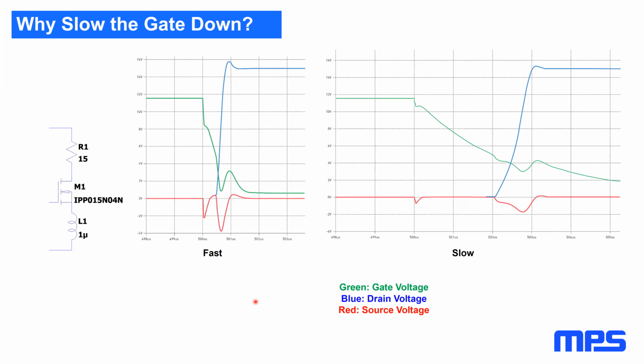From there, that'll give you a minimum. So there's no disadvantage to using a bigger gate driver because you can always slow it down. You can always insert some resistance. The downside is higher current gate drivers are going to cost more money, and quite often they're physically larger. But there's no downside because you can always slow things down. On the other hand, you can't speed them up. If your gate driver can only do 100 milliamps, you're going to be limited with whatever it can do.